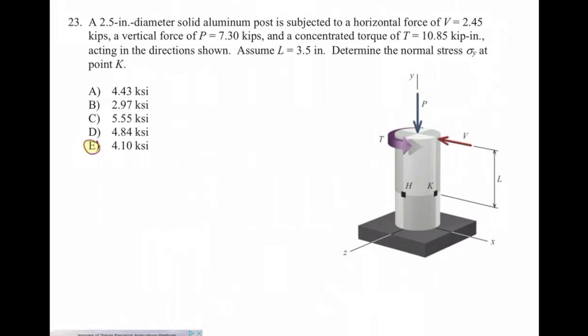Here, we can simplify that. Why? Because here we are just looking for the normal stress. For normal stress, should I take care of the torque? Torque doesn't play any role, so just ignore that. Should I take care of the shear force? No. What about Q? None of them. So I will just focus on determining the axial force and the bending moment.